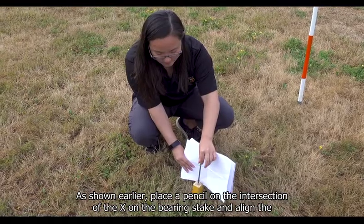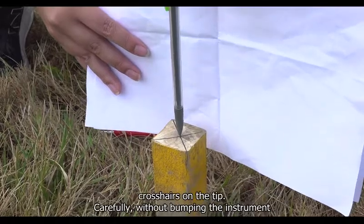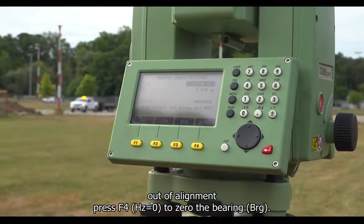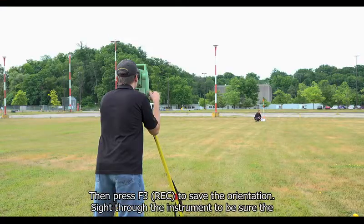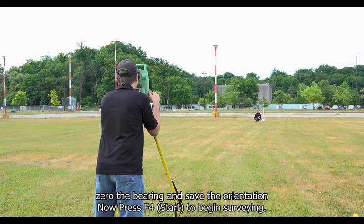As shown earlier, place a pencil on the intersection of the X on the bearing stake and align the crosshairs to the tip. Carefully, without bumping the instrument out of alignment, press F4 to zero the bearing. Then press F3 to save the orientation. Sight through the instrument to be sure the crosshairs have not moved off the target. If they have, repeat the previous step. Realign, zero the bearing, and save the orientation.